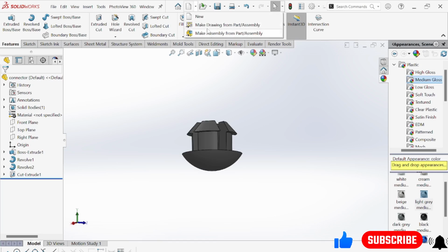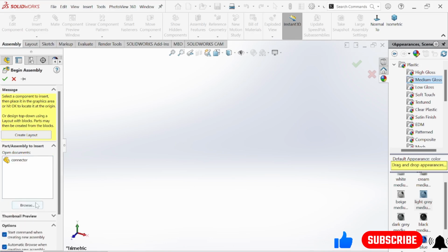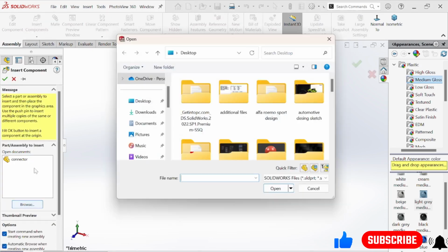This time we have to select the third option. This one is for making drawings, I will tell you later how to use this. Make assembly of the part. Now when you select this one, it will come like this. Again, go to connector, select this one. Now here you see the connector comes. Again, go to insert component, go to browse.